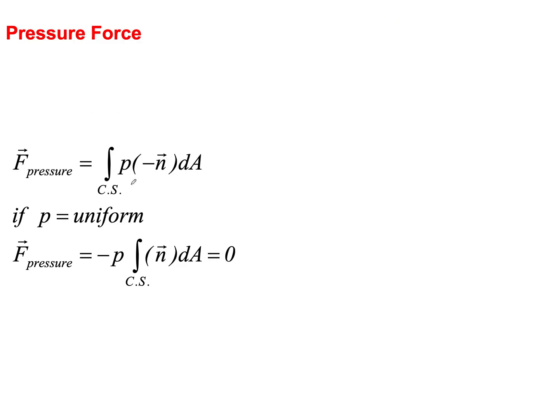So that's the fluidic effect. If you look at the pressure force, the pressure acts compressive, so it acts towards the area, and here the N is the unit vector pointing away from the control volume. That's why the minus sign tells you it's compressive. So the pressure force will be pressure times the area, and those two signify the direction. The minus sign signifies that it's compressive towards the surface. So that's the pressure force.